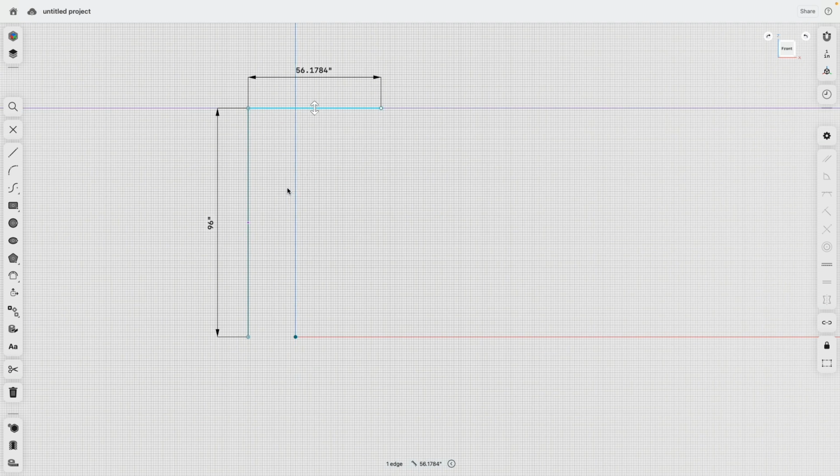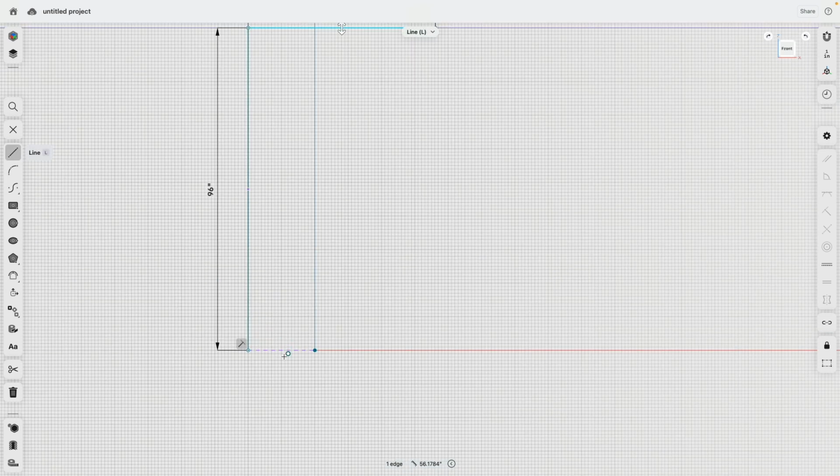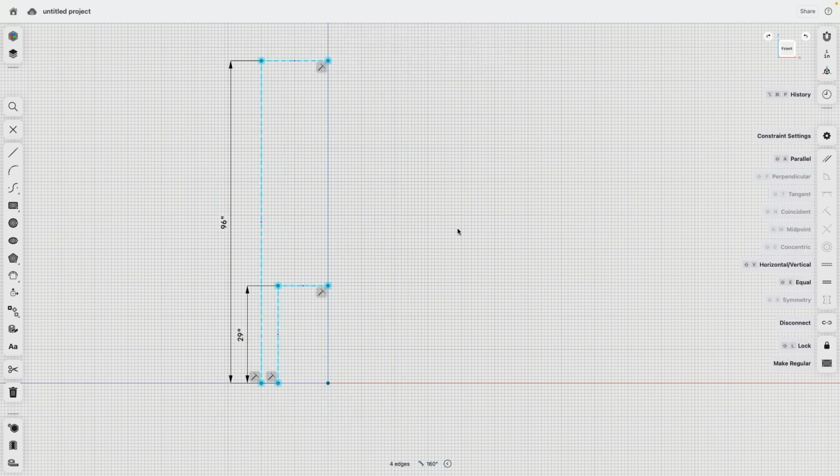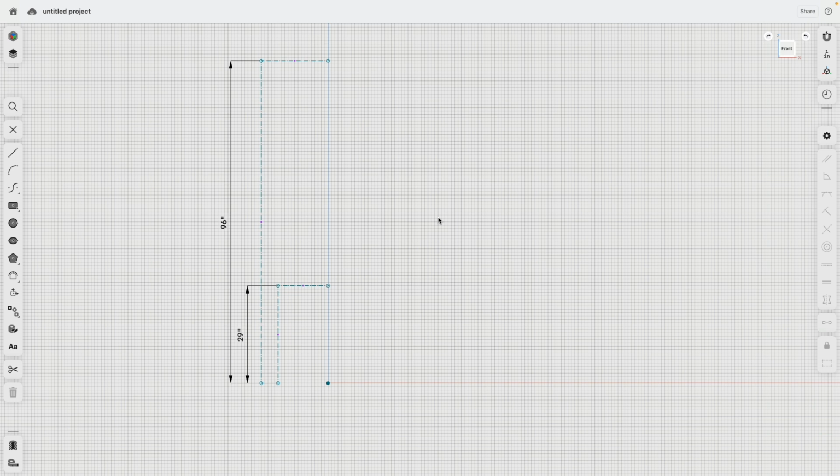The second object we should measure is also our work surface. 29 inches, 30 inches, for example, is a table. So I can draw a line up, 29 inches, click, go horizontal, click. That is now where, let's say this is a dinner table, your food would be. And now we have the space in between to play with. Great. To tidy stuff up a little bit, I bring these lines over so they're perfectly vertically aligned. All those are just helpers, so let's make those construction lines.